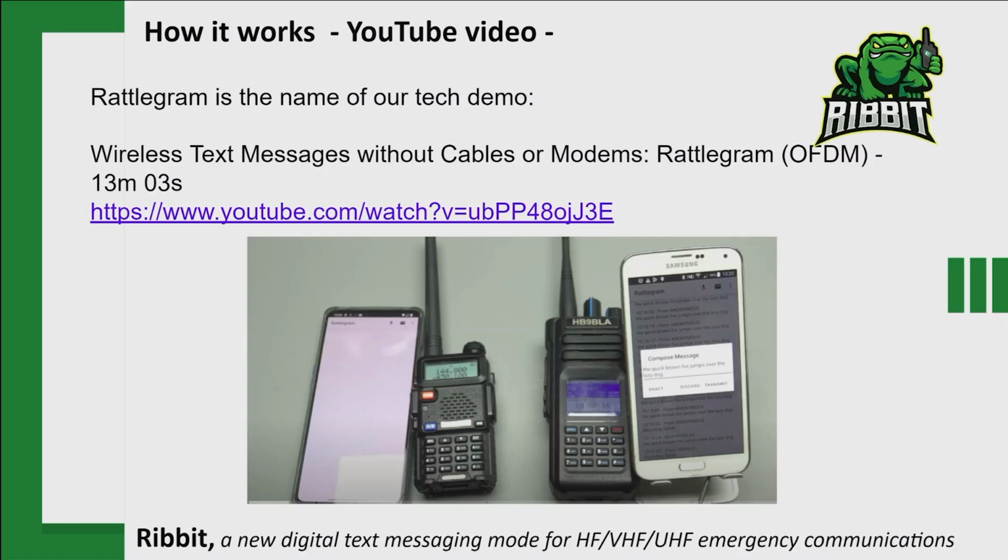That's right. In the early days of analog modems that would go over your phone line, when they went from 300 baud, 9600, 14,400, and then 56K, you had that research around how can I encode the most bits per second over audio. One thing that it didn't have to deal with was the multipath reflection, because they had the benefit to be directly coupled on the audio line, so you wouldn't have the multipath reflection that we need to take care of.